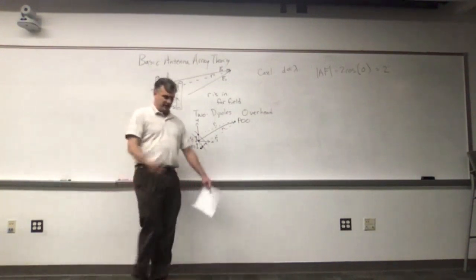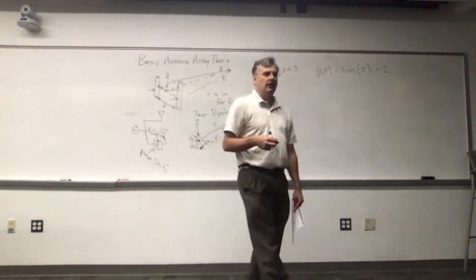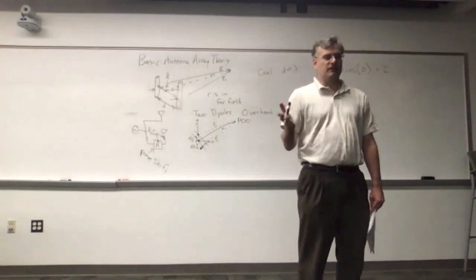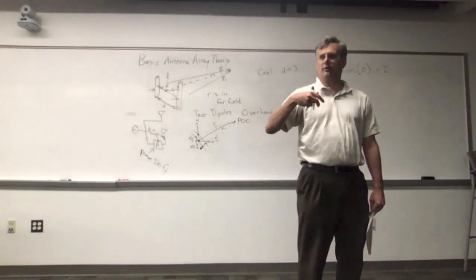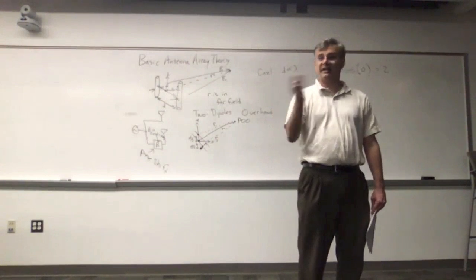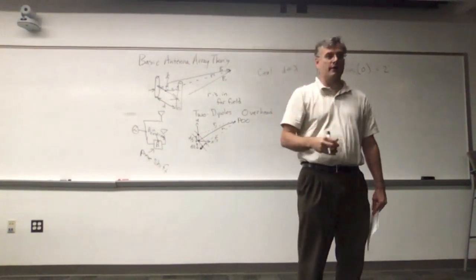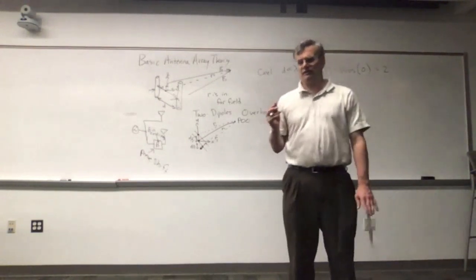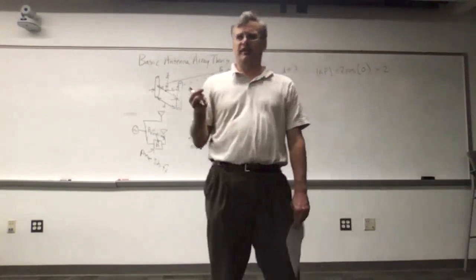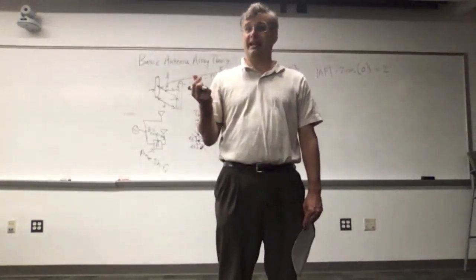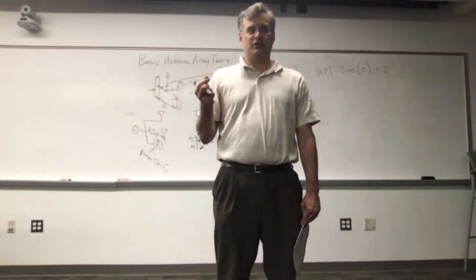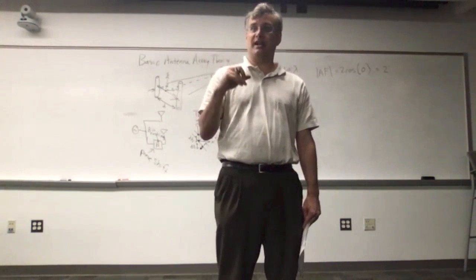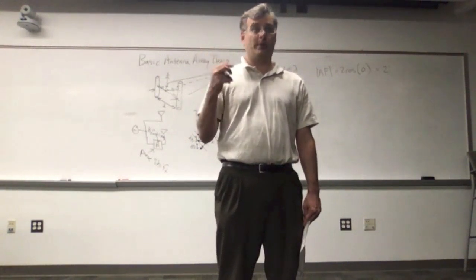one way to do that is just by adding an extra length of wire. And if you want an adjustable beta, you can just put different lengths of wire and put like a multi-pole switch to connect them. And you connect different lengths of wire if you want to digitally dial in different phase lengths. There are also analog phase shifters. You make them usually with some sort of nonlinear material. At lower frequencies, you have to use magnetic material because you can basically change the mu by saturating DC bias or unsaturating the DC bias with an electromagnet.